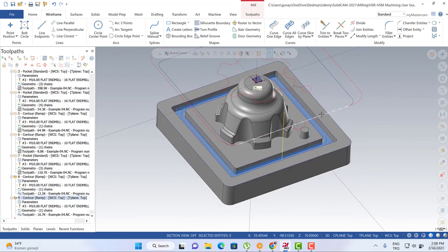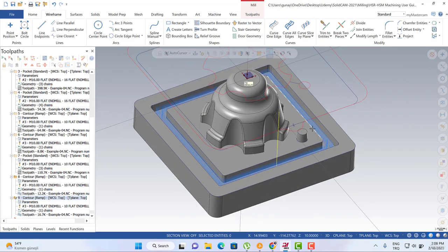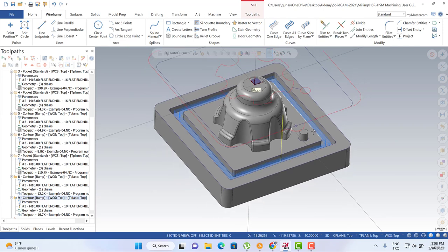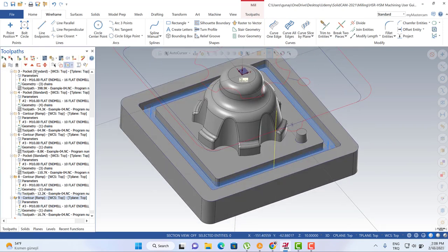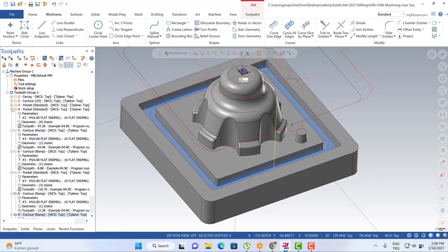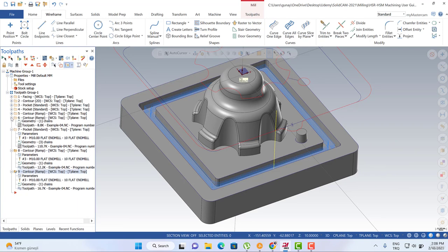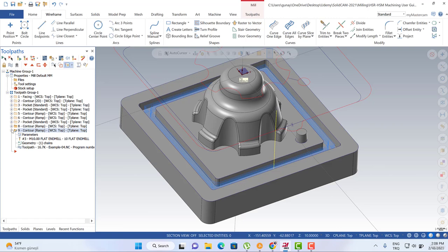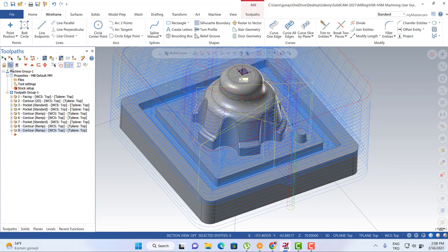And at the end of this section, we're gonna see our final position. If you would like to use some roughing and finishing process, you can also copy that toolpath, and then maybe you can also create a new tool here. It's also possible. Anyway, this is our finishing process.